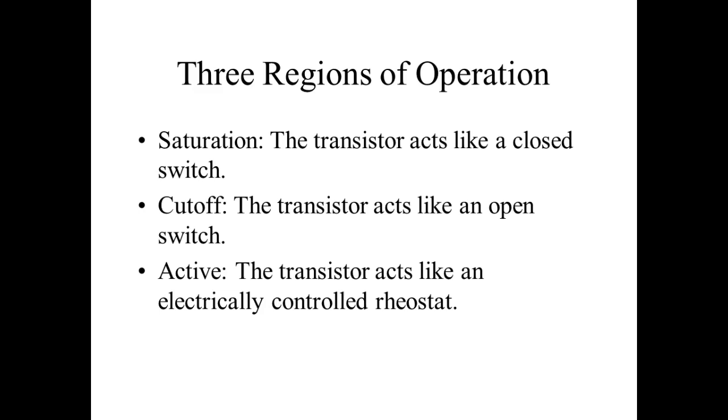Then cutoff, the transistor acts like an open switch. So to operate it like a switch, we switch it between saturation and cutoff. That's what we do. Y'all understand that? We do that all the time.